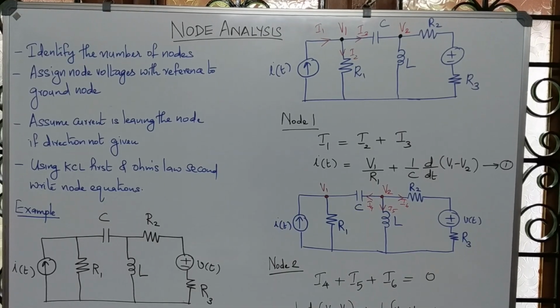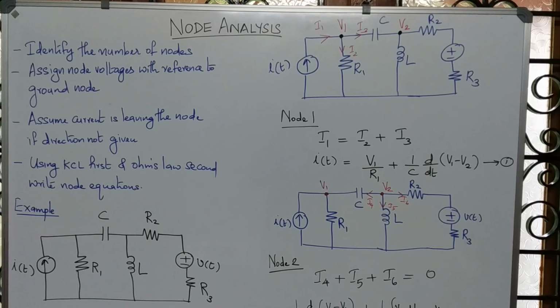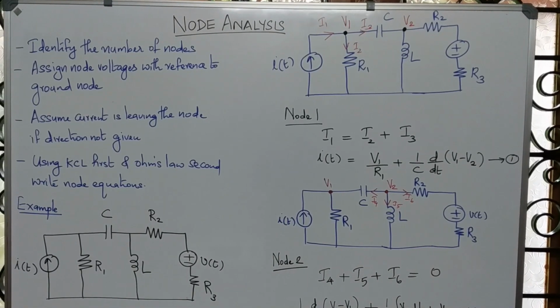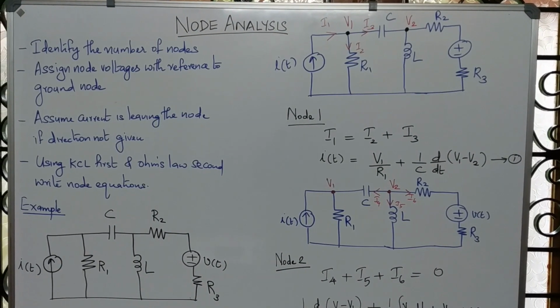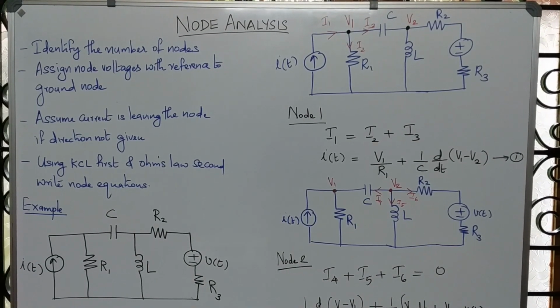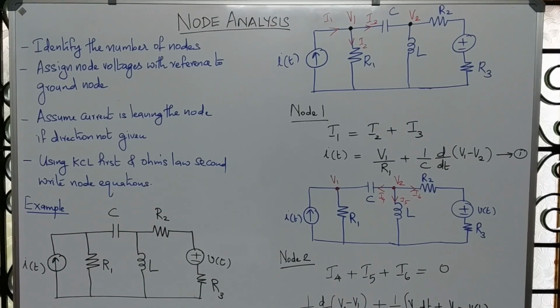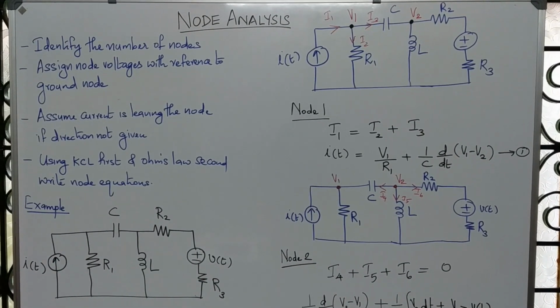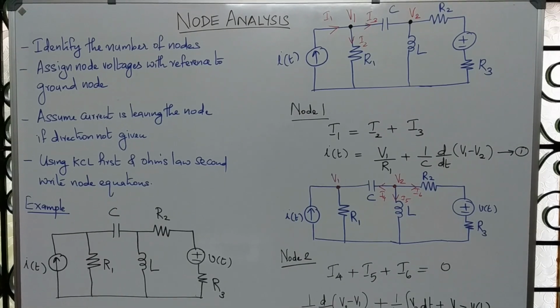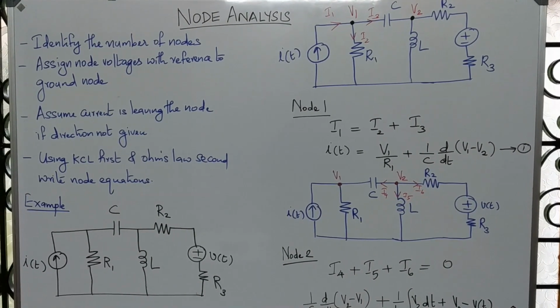Today we'll move on to the most important topic of our first module, which is node analysis. As I said earlier, there are two basic ways in which you can analyze a network. The first one is node analysis and the second is mesh analysis. Node analysis is based on Kirchhoff's current law.